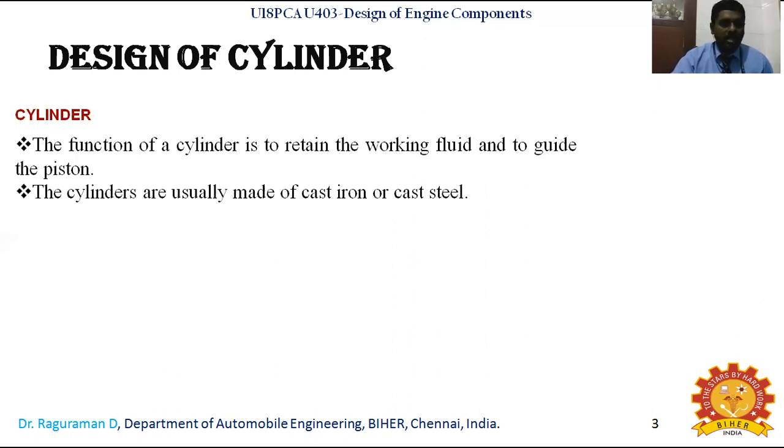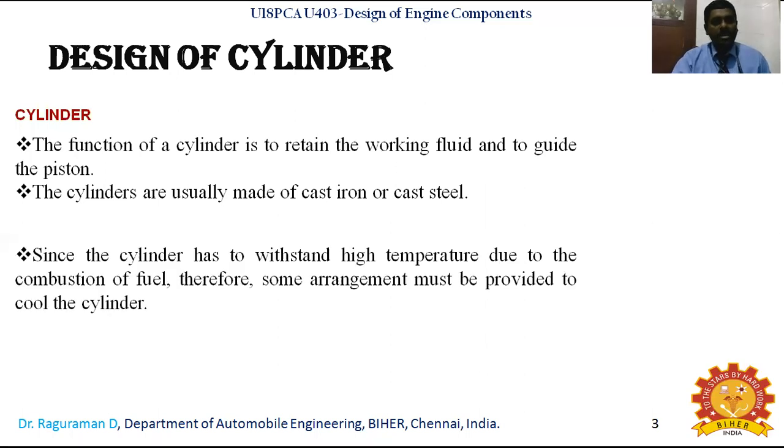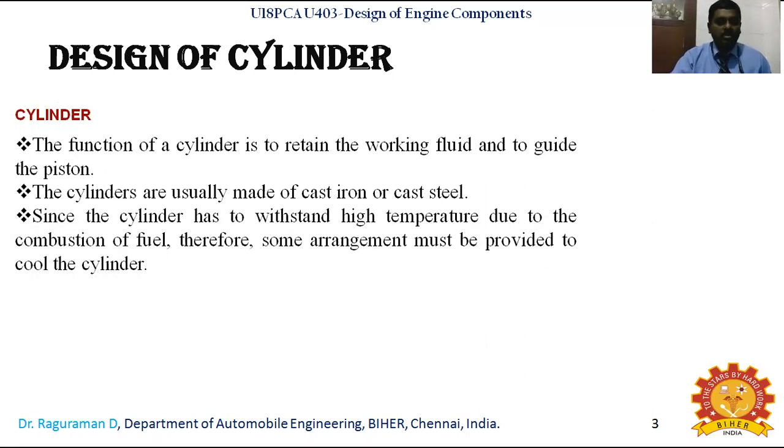So what are the cylinders? It is usually made of cast iron as well as cast steel. Since the cylinder has to withstand high temperature, because as the fuel undergoes combustion it is going to have a high temperature, the cylinder should be designed keeping that in mind. Therefore, some arrangement is needed to cool the cylinder. That is why you have to make a cooling system in the cylinder liner also.